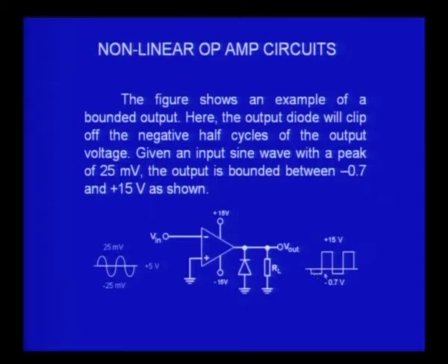It is only minus 0.7 to plus 15, which is almost like 0 to plus 15, and therefore this can perhaps be used in different circuits for digital applications and things like that. So, this is one way. It will also be still better if I can control the two voltages on both sides, plus 5 to minus 5 or plus 3 to minus 3 and things like that.